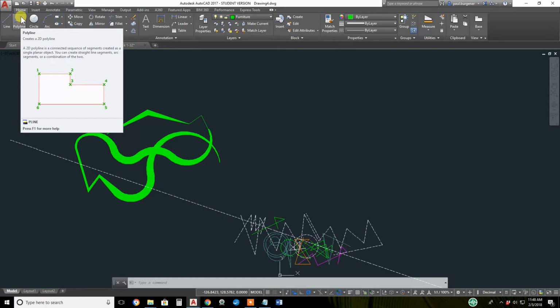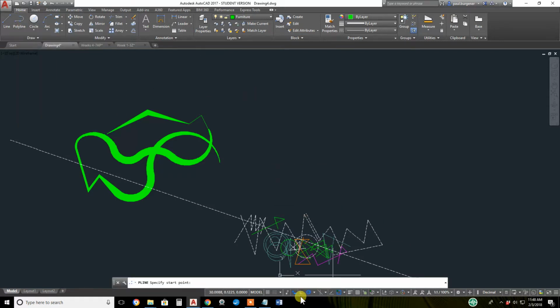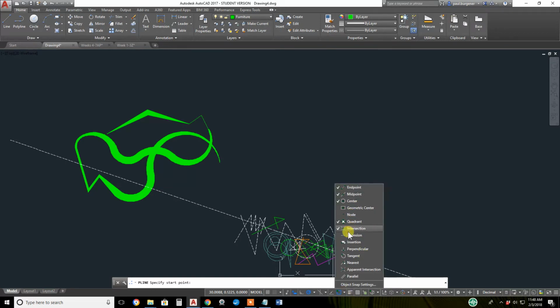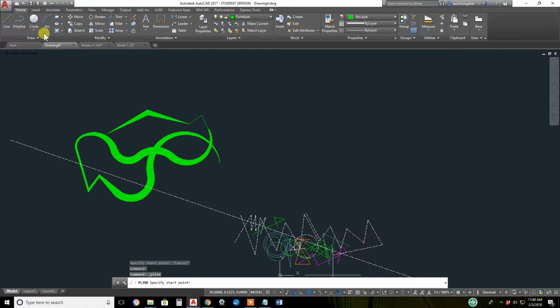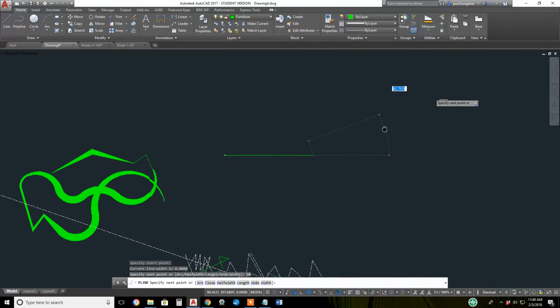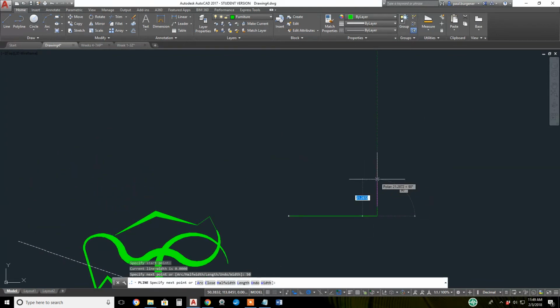a circle. So let's click on the polyline with dynamic input, polar tracking, and object snaps on, again with Burgener's 5 favorite object snaps. Let's start a polyline, click somewhere. We'll set it at 0 as it currently is from practicing here, and just draw a floor plan real quick. Say, I don't know, 50 feet. We'll say an AutoCAD unit represents a foot now.